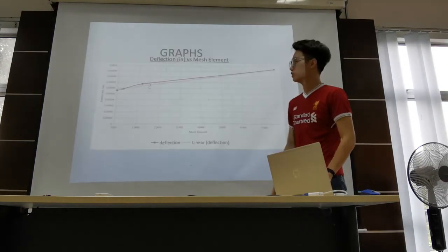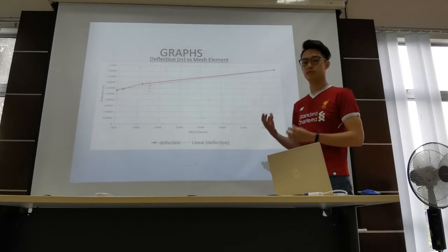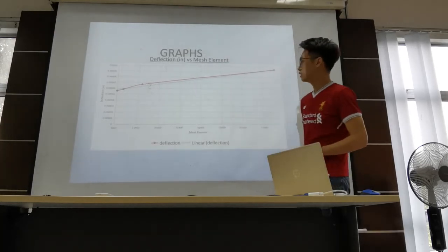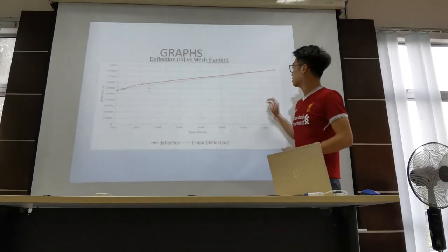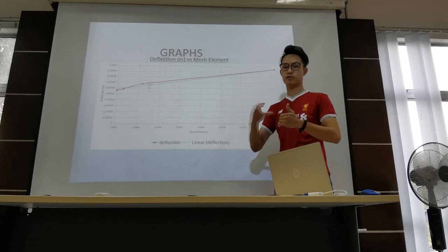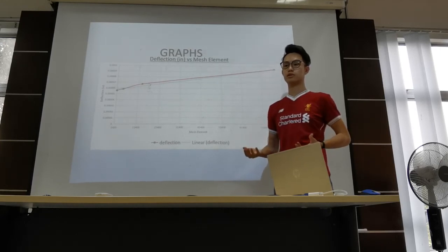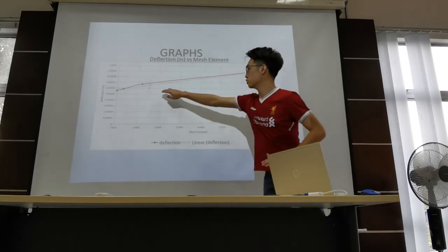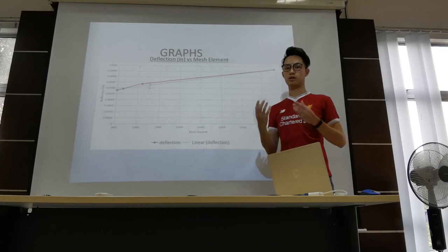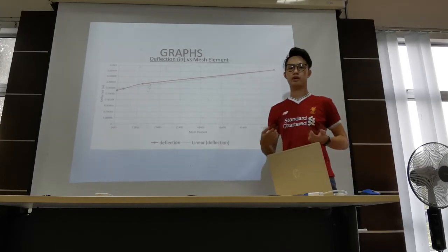After that, we will see a brief representation of the number of elements versus the deflection at the edge of the table. As we can see, the higher the number of elements, the higher the deflection. But this is due to the accuracy of the simulation improving with the increasing number of elements. Unfortunately, we didn't have the full version of FEMAP NASTRAN or a very high-power computer. If not, we should be able to observe a flat line after a higher number of elements is implemented in the simulation. So now, all we can say is the higher the number of elements, the higher the deflection is.